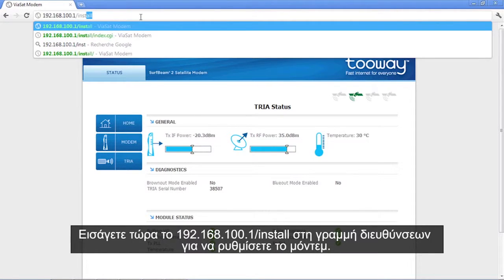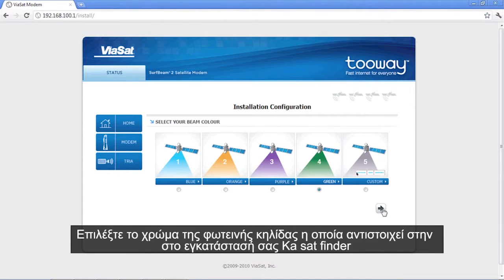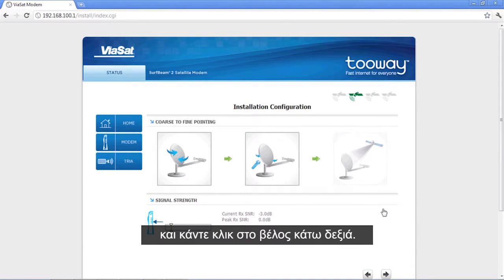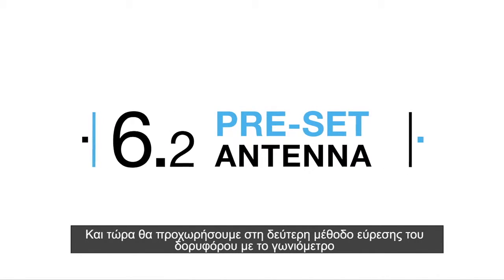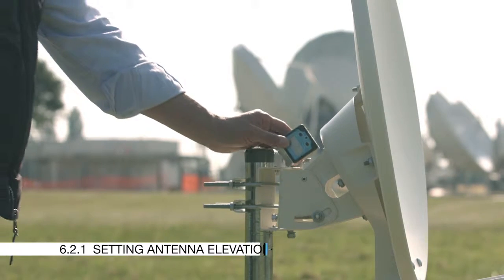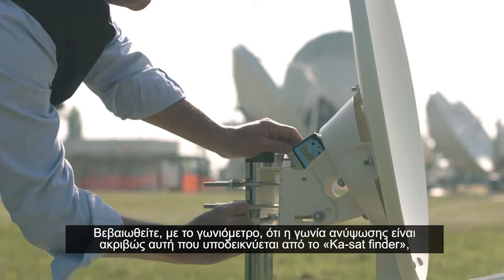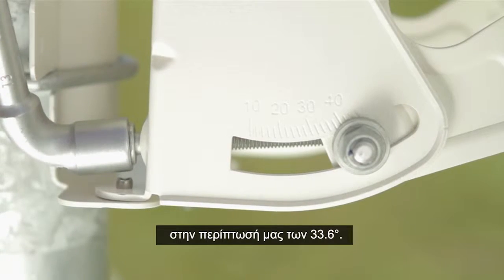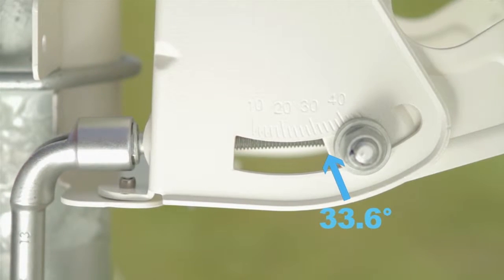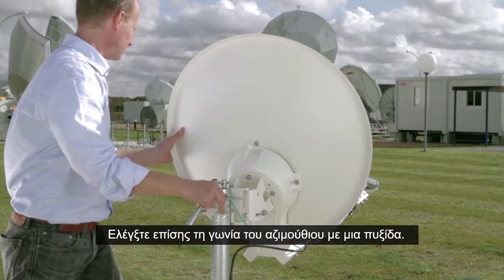To configure the modem for installation, enter the address 192.168.100.1/install. Now you highlight the spot color indicated by the Kasat finder and press on the arrow on the right-hand side. You now enter a new screen for antenna pointing. Check that your elevation is correct with the inclinometer. In this case, it is 33.6 degrees. Check your azimuth angle with a compass.